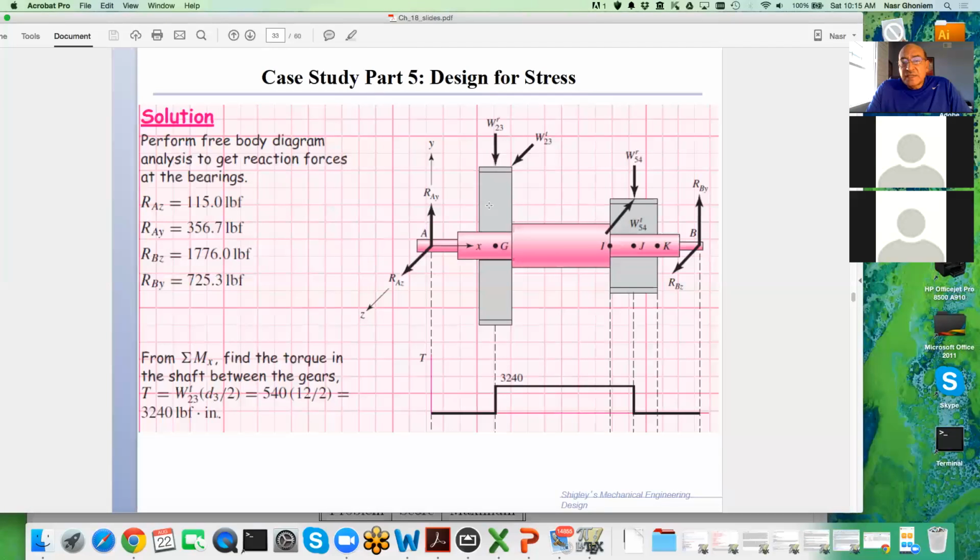So if we take the shaft that contains gear 2 and gear 5, then gear 2 has a force that is decomposed into a radial 2-on-3 and a tangential 2-on-3. And gear 5 has also a radial 5-on-4 and a tangential 5-on-4. And we learned in the class how if we take the system, these are two planes that are perpendicular, and on each plane we can do the statics independently.